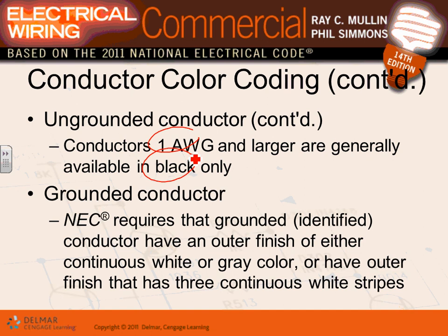The other one you put a red tape on it. The third one will put blue tape, and the fourth one will put a white tape. And you got yourself a 3-phase 208/120 system. Any comments, guys, about re-identifying the feeders and the branch circuits in the field?